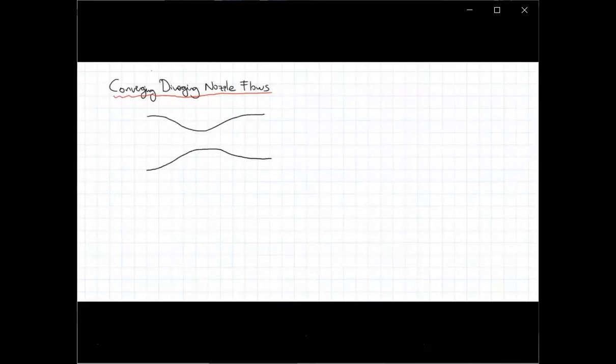So the flow comes from left to right and starts with a region where it's basically subsonic with some certain inlet conditions, stagnation pressure and temperature, and then reaches the sonic Mach number at the minimum area location, and then after the sonic Mach number reaches supersonic flow conditions. So we are basically talking about this internal flow problem.